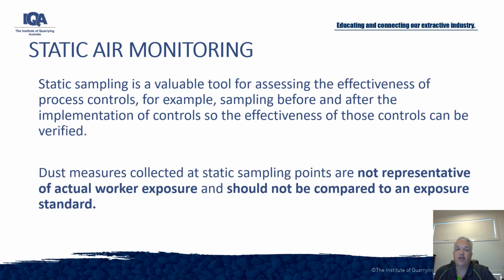So static monitoring is a valuable tool for assessing effectiveness of process controls. For example, sampling before and after implementing a control to determine if the controls that you've implemented are actually effective. Dust measures collected at static points are not representative of actual work exposures and should not be compared to exposure standards. It, however, is a good indication if the controls are adequate to minimize the dust levels.